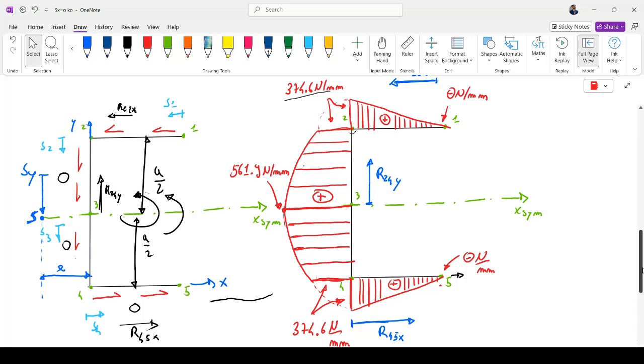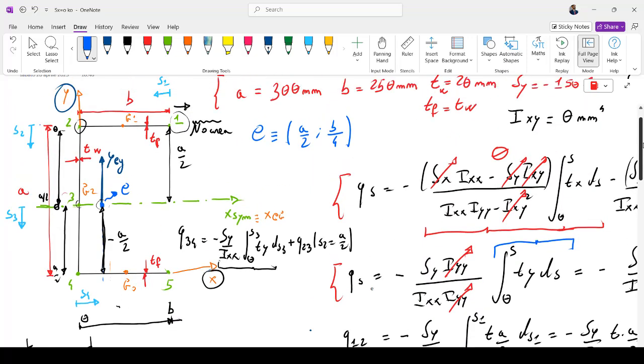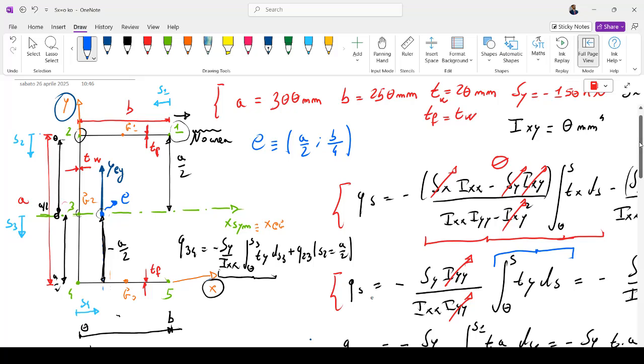Now on the channel I have also made another video where I calculated the shear flow of this quantity. It is in Italian language, but I calculated the shear flow with another strategy, avoiding the integral. Now I calculated the shear flow of the same channel shape using the integral and the conveniently chosen abscissas S1, S2, S3, S4. This is the method suggested by T.H.G. Megson, and it is clearly more powerful with respect to the strategy that calculates the first moment of area of a part of the whole of the single rectangular shape and so on, as described in the past videos.